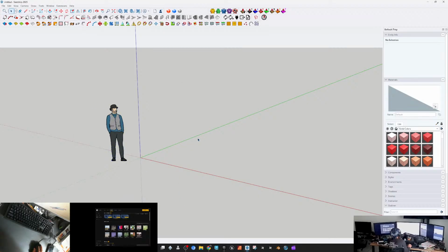A couple things to consider. I use PBR materials. You can browse the internet and find a lot of those for free. You can find some on the Fab Marketplace. In many instances, you can create your own, but since most of the people that I'm targeting here are probably fairly new to 3D, it's probably best that you stick to, if you are going to use the SketchUp to Unreal Engine method, bringing in materials inside of Fab directly to Unreal Engine.